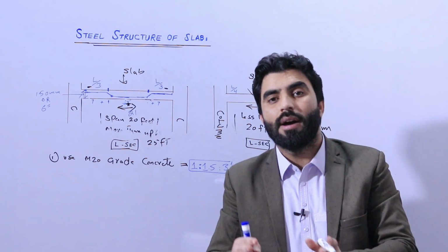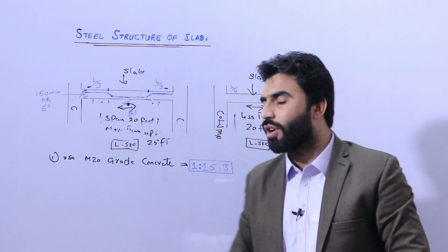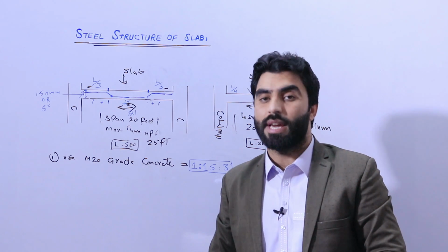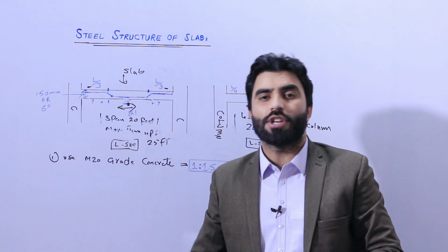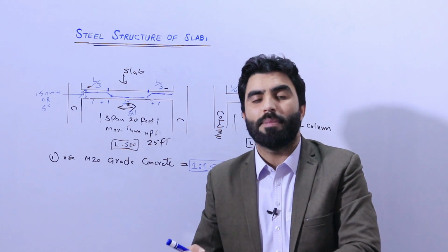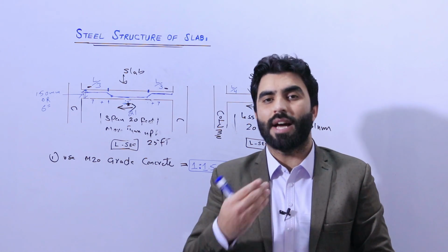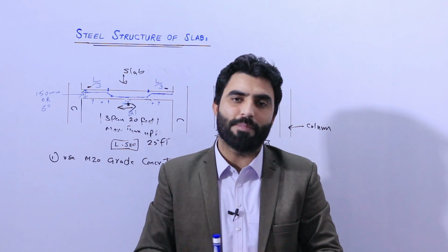So crank bar or bent up bar is economical compared to extra steel rods, but in many constructions, by myself, I am using extra steel rods. Extra steel rods, we are providing a singly mesh, and on the top of that the other mesh, which is called doubly mesh. So the singly mesh is placed at a spacing of 12 inches, and on the top of that we are providing the other spacing of 12 by 12 inches. So at cover, it becomes 6 by 6 inches.